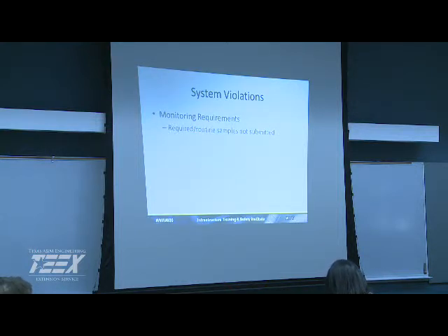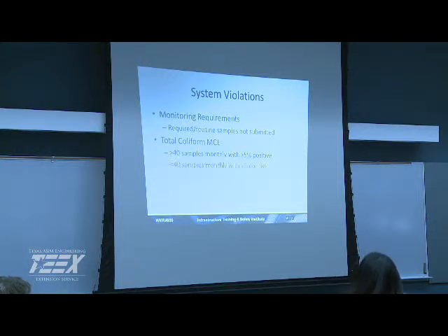Monitoring requirements. You are in violation if you're not pulling your regular samples or you're not pulling your repeats like you're supposed to. For your MCL, for your total coliforms, nobody in here is pulling more than 40 samples, but if so, it's a 5% rule. If you're pulling less than 40 samples, you get a positive, you got a violation. So you got repeats to do and all that other kind of fun stuff.